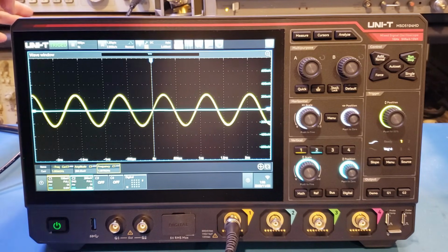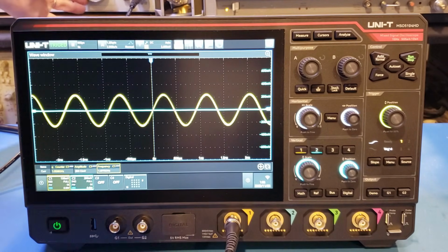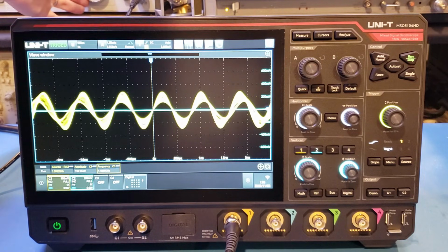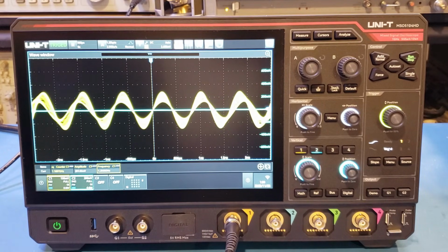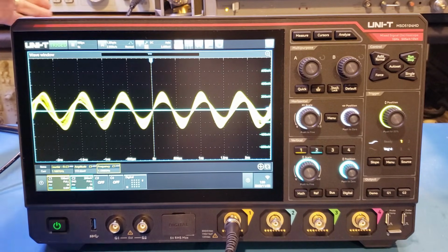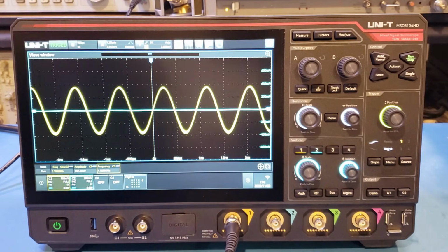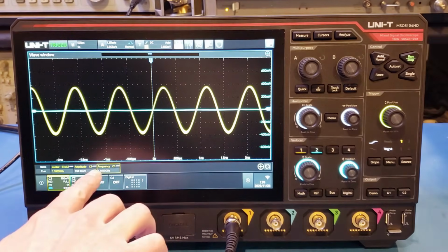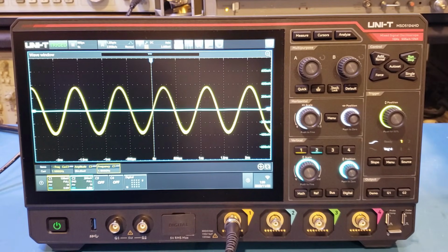So now we're at 1.4 gigahertz, and that's actually still not right. So 1.3, yeah, you can see, okay, 1.2, 1.1, so let's do 1.2. You can see that essentially anything above 1.1 gigahertz, we're not able to reconstruct, but there's definitely no problem with the 1 gigahertz bandwidth. So right now, for example, we're at 1.1 gigahertz, and you can see that we're able to measure the 1.1 gigahertz and also reconstruct the sinusoidal with no problem.